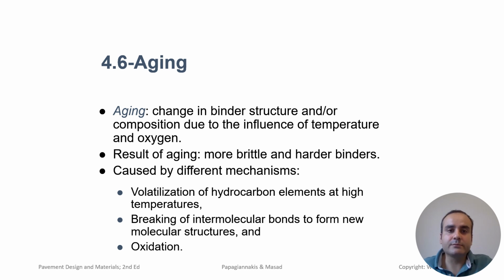It's a result of exposure to high temperatures and air while the mixture is being processed. Long-term aging takes place over the pavement's service life, as the binder is continuously exposed to environmental conditions like UV radiation, oxygen, and fluctuating temperatures. Aged binders lose their flexibility, which can lead to premature cracking, especially in colder climates where the pavement undergoes thermal contraction.